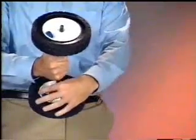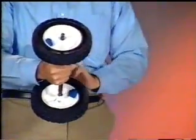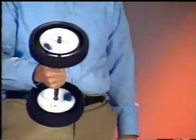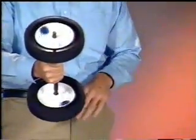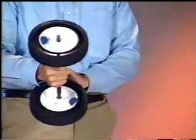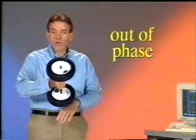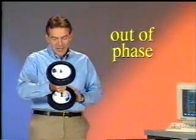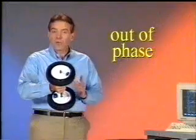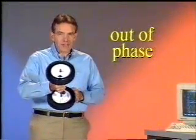If we move one unbalanced weight to the opposite side of the wheel and spin it again, the weights pull on the shaft, but each end is pulling in an opposite direction. Any condition where the wheels are not pulling in the same direction is called out of phase. In this particular case, they're pulling exactly opposite, or 180 degrees out of phase.